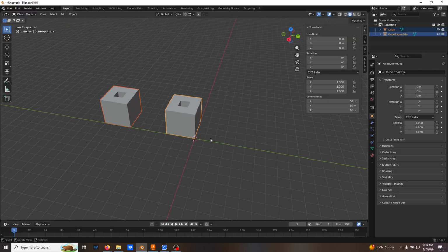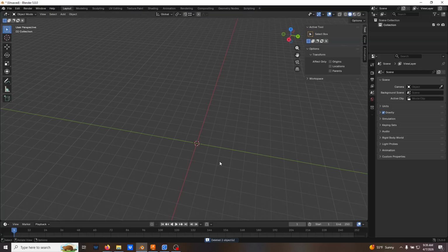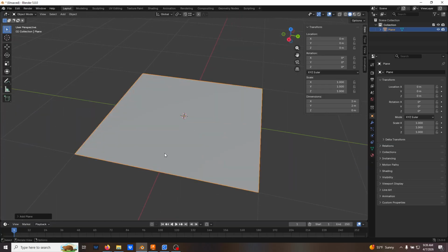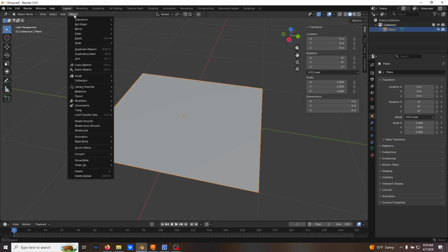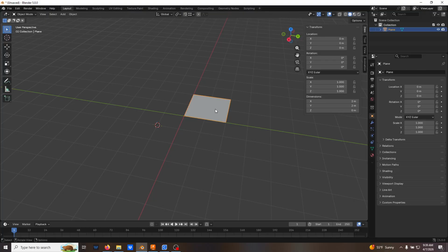What I'm going to do is delete everything again, because I'm going to do 2 more ways of creation. I'll delete one more time, and then in object mode, Shift A, I'm going to add a plane mesh, period on the keyboard to zoom to it, tab, point select for 1, Shift S, cursor to selected. I'll tab back in object mode, go to Object, Set Origin to 3D Cursor. There we go. Alt G to clear my location. And then I'm going to scale by 15.